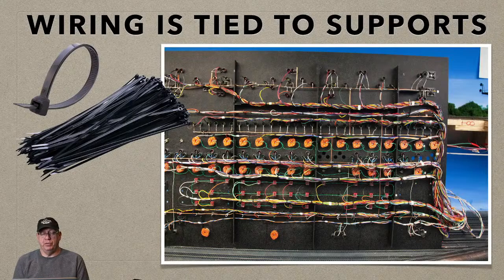Here is the beauty of using those vertical bars and those horizontal bars that are glued out of ABS. They're ABS strips, basically 1.5 inches tall, glued to the back of the panel. It gives the front of your panel strength, but it allows you to do a beautiful, really nice job of wiring your layout. So everything goes through these horizontal, basically pigtails we call them, and there's wire tied to the frame.